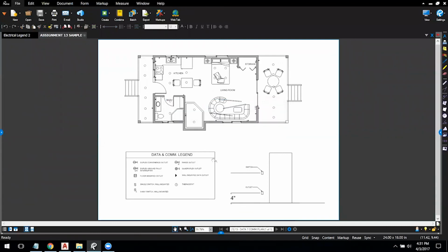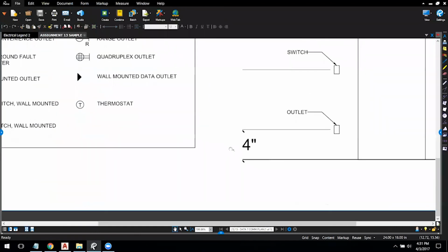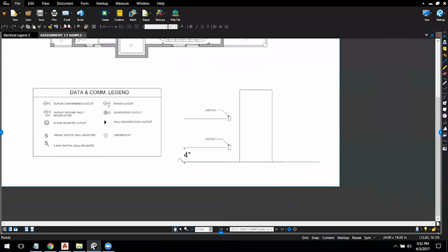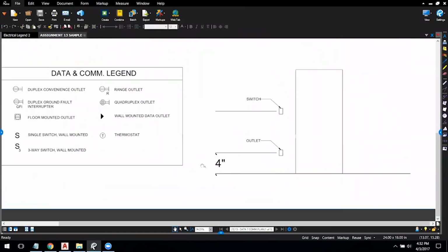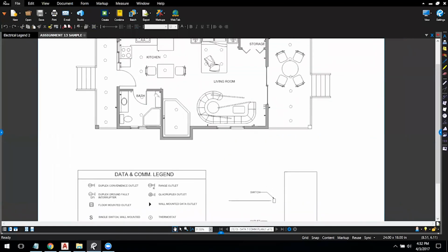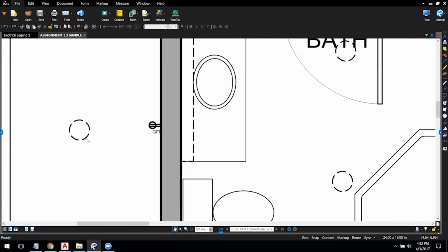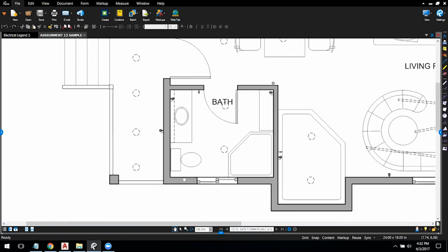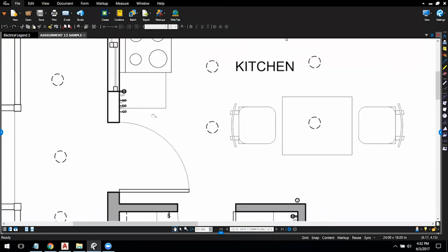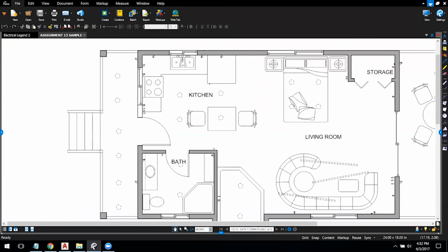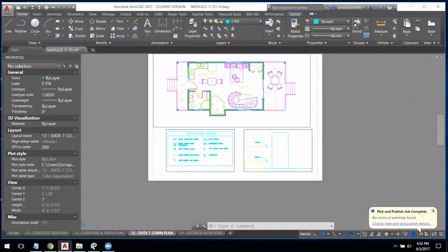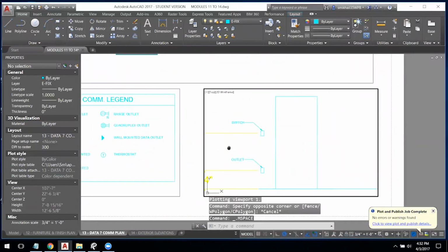And when we look at it in our drawing, it should be something like that. Okay, be careful with the dimensions in here. So my dimensions, first of all, are too big, and second, they're cropped. So I need to make sure I show these. And here I should be able to see my light fixtures hidden, which is mean dashed. And I should see all my outlets and my switches in my project. Okay, so please always look over before you send it over, so you can notice these things in advance prior to me redlining it for you.